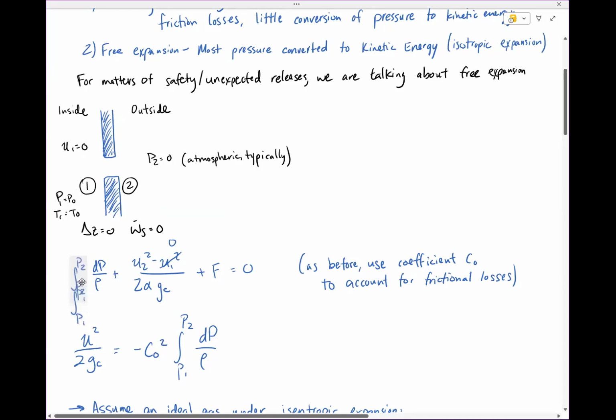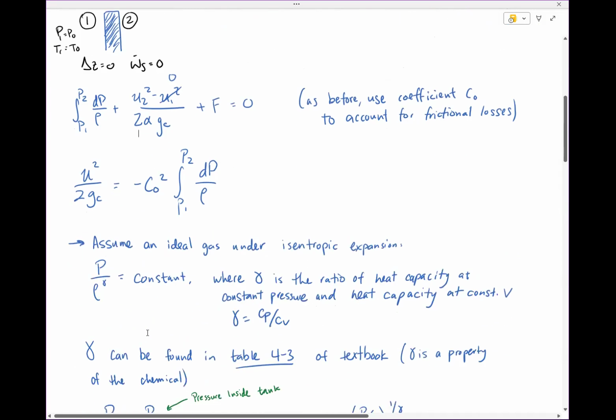This should be a little bit higher. There we go. So this is our energy balance after we cancel stuff. Just as before, we've got this frictional term that we need to choose how we're going to deal with it. We will do the discharge coefficient thing again. This is how we define the discharge coefficient, by the way. This is just a definition, and we will rearrange things.